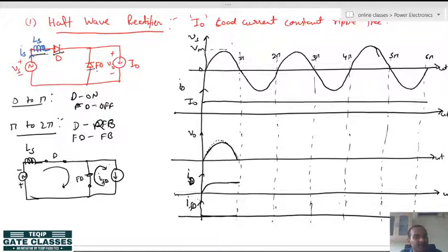Okay. So, what is happening here? The diode current is gradually decreasing and the freewheeling diode current is gradually increasing. So, for a little time, let me draw it like this. Now the diode current will gradually decrease, and the freewheeling diode current will gradually increase like this.